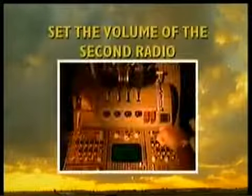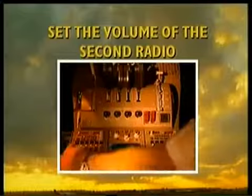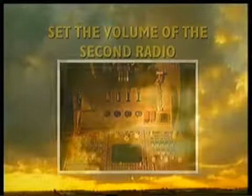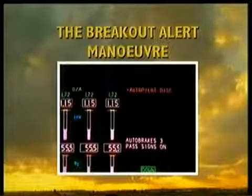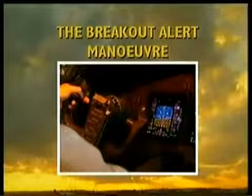Set the volume on the second radio so that both volumes are at about the same level. This will ensure that if there is a breakout alert, you will hear the transmission. Hand fly the breakout maneuver and carry out the maneuver as quickly as safety permits. When stabilized after the initial maneuver, follow your company's standard operating procedures.